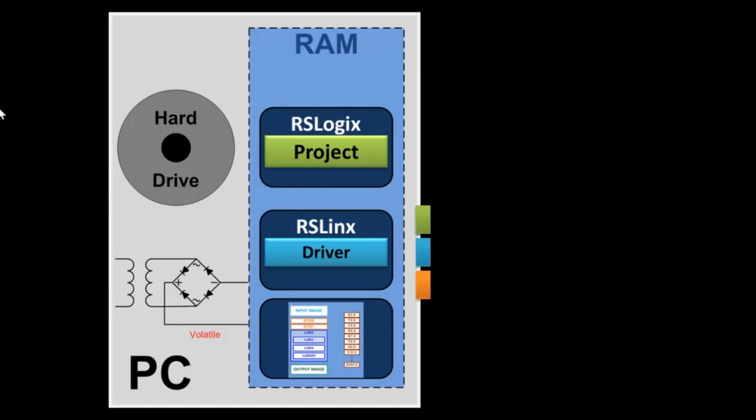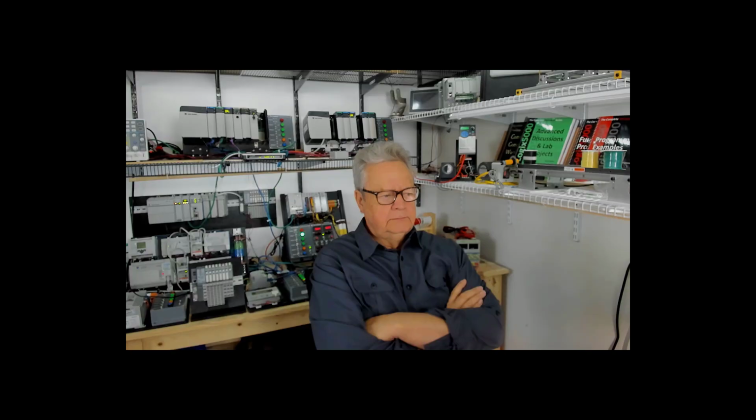Once you're online with it, you can download a project from RSLogix into the Emulate, and you can upload from the Emulate into RSLogix. However, Micrologix 1000 does not support online programming, and in the case of RSLogix Emulate 500, it does not support online programming anyway. So the only real difference between a PLC that you might have had out there to connect up to and Emulate is you will have to do all of your editing offline.